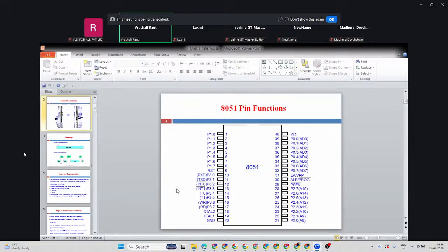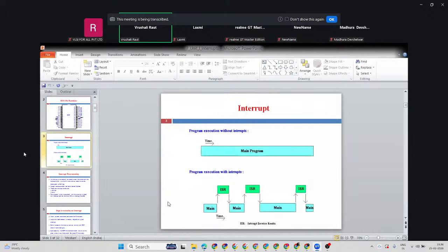So which one is the priority interrupt? Whether the door is closed or not, that is the priority. Who is going on the second priority? Second priority, obviously, if the door is closed, it will check for the water, right? That is the second priority. So that way interrupts are there. That way we need external interrupts, right? And they are playing a very important role in our program. So do you understand? These are the interrupts. The more interrupts, the more external things we can check for. Okay, now we'll check what different interrupts are there in 8051.